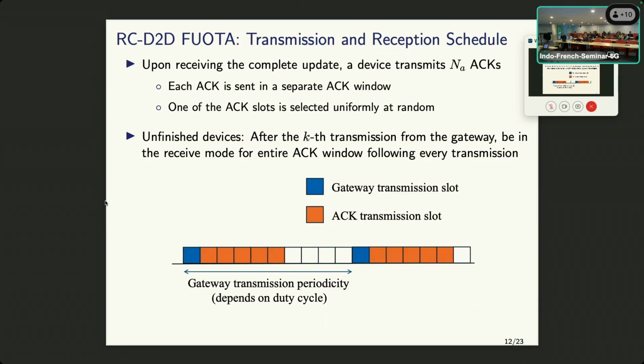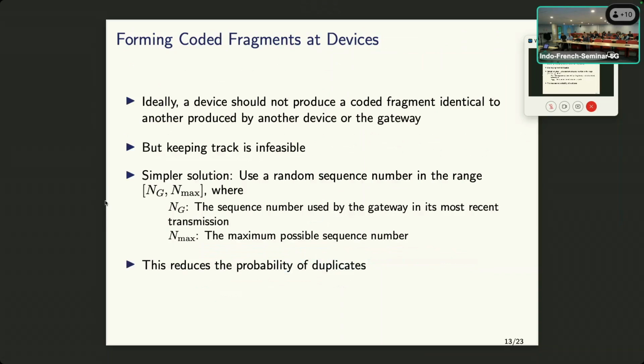And for all the unfinished devices, they will be in the receive mode during this entire time, from the starting of the gateway transmission slot to the end of the corresponding acknowledgement window. So the extra price we are paying in terms of energy spent for listening is this extra time. Normally they will be listening only this, now they are listening the entire duration. So that's one point regarding transmission.